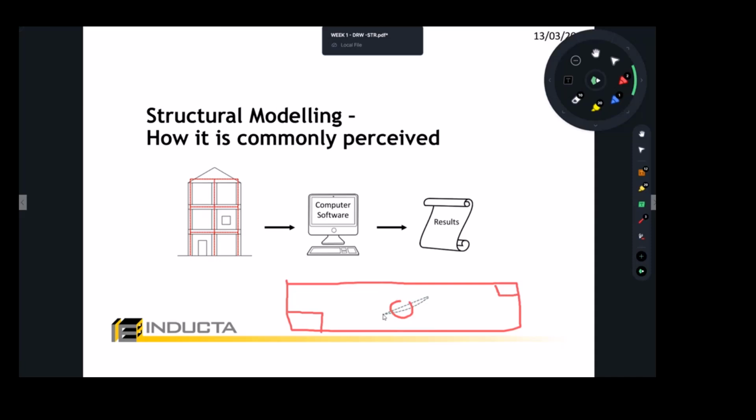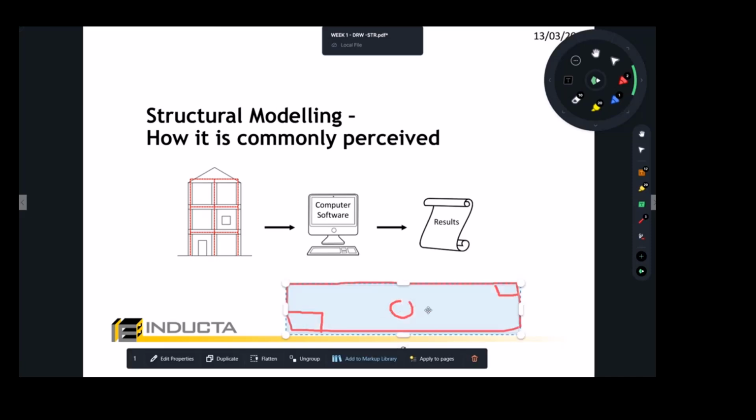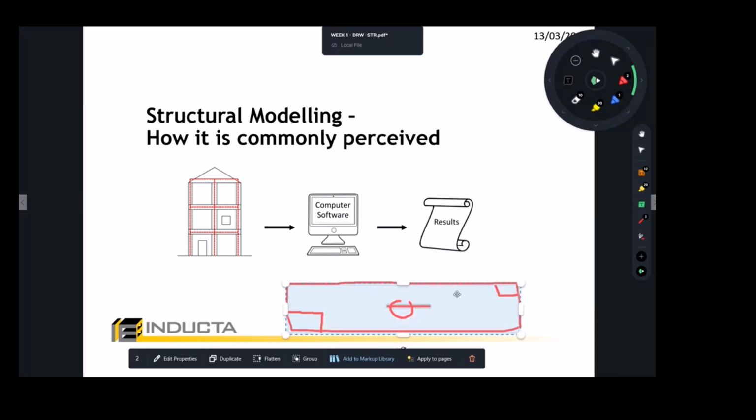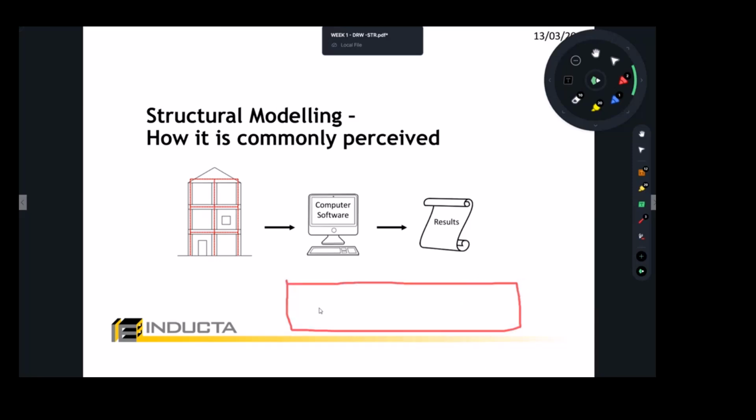If this is not possible, let's say we don't have one here, we don't have one in the middle, then that means it may not be enough to stabilize it by two corner cores, or they may not be large enough, etc. Then in this case, you may end up required to use portal frames. Okay, so something like what we're seeing here.